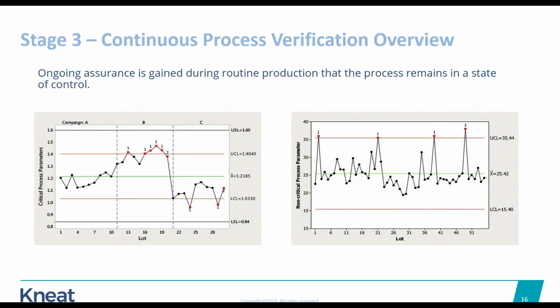So also at this stage, you are given the opportunity to look at the parameters. If there's one that's continuously out of specification, you can assess it, determine the root cause of why it continues to be out of spec, and then also come up with a path forward on that. So we're getting into the corrective action, preventative action type deal there.